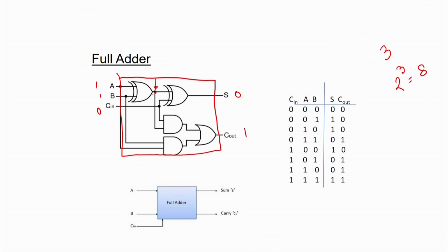So, once we get a stable output, then only we can work with this particular second gate, because Cin is coming immediately as soon as I give the input, but the second input to this particular XOR will come after some unit of time only, which depends on the propagation delay of this particular gate, and this second gate will also have some propagation delay.